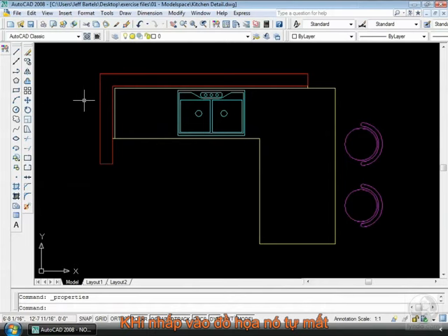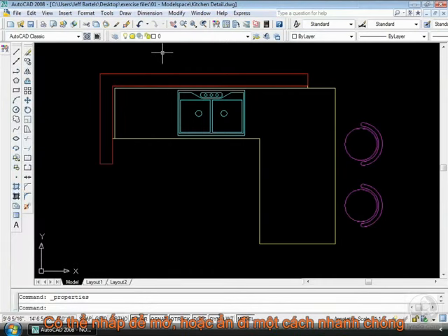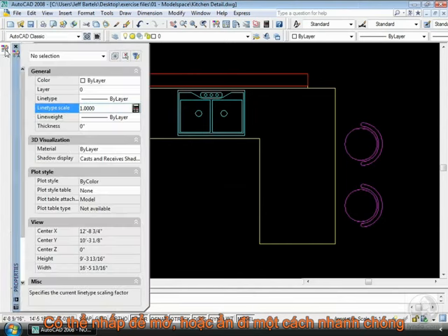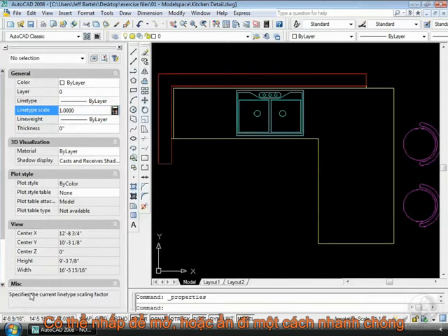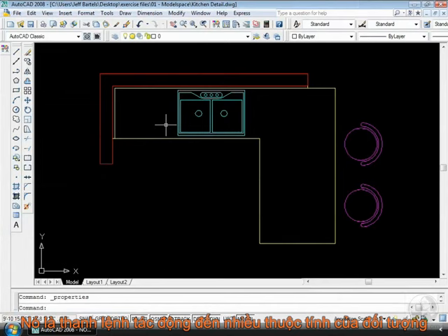This means if I want access to this palette, I just have to move up over this icon, hover, and it's available. I can move away and it closes. If the time comes when I'd like it to be on my screen for a significant period of time, once again, I can hover over so it opens. I can come down and click my Auto Hide button. It will remain on my interface as long as I need it. If I want it to go back to the anchored state, I'm going to come over and click on my Minimize button to collapse it back down to the toolbar icon. Palettes are the most versatile tool in our interface. They combine the functionality of a dialog box with the flexibility of a toolbar.